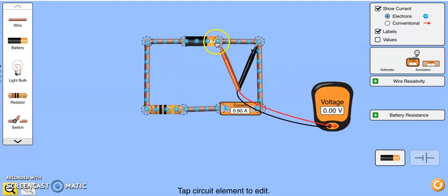What that's telling me is I already know the red is at 9 volts. Well, then this part of the wire must also be 9 volts. So the difference between these 2 points is 0. And what's important about that is no energy is being used. There's no joules given up for every coulomb that moves through. So these are ideal wires. They're just acting as conduits.